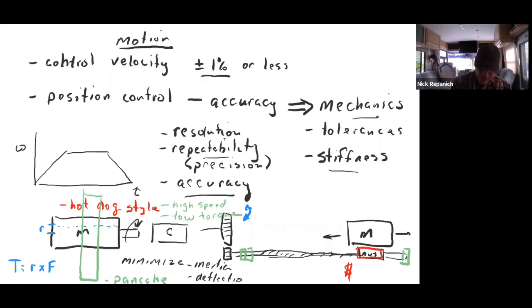That is when you deal with R cross F, R is large, right? And so the force may be less, but the R is large. And so you get a lot more torque out of that motor, but it's got a lot bigger bearing. It's a lot more expensive motor to make. Anytime you get a larger bearing and try and hold tolerances at a larger diameter, it gets more expensive. And so direct drive motors, pancake motors are kind of expensive. Linear motors are kind of expensive compared to an easily manufacturable hot dog motor that is high speed and low torque.